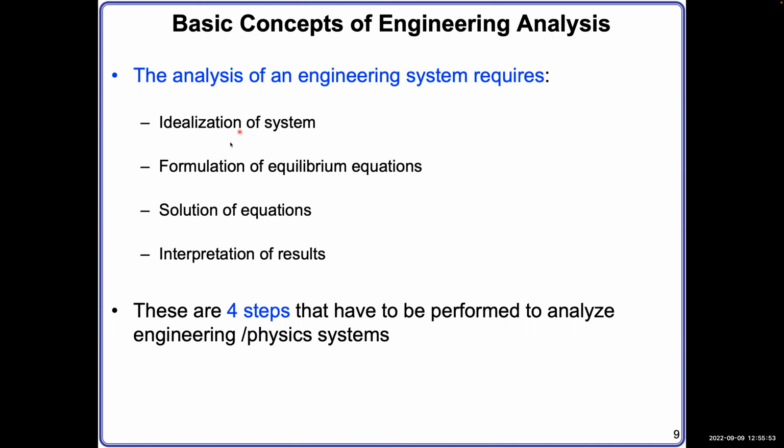The second step is to look into the system and find out the physics or mechanics equations involved, especially equilibrium equations. In physics, you have energy equilibrium. In mechanics, you have force equilibrium and momentum equilibrium, both linear momentum and angular momentum, for the static problem.